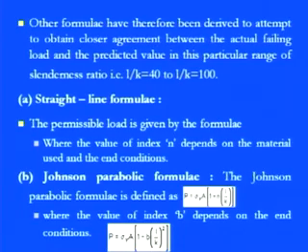But again, with all the nonlinearity and the realistic nature, we need to incorporate nonlinearity in calculating the crippling load in the Euler theory, or we can say we need to incorporate the eccentricity. Then we can figure out, if the eccentricity is in microns or even millimeters, how it will introduce the moment and add up in the final crippling load, so as to calculate the buckling in a realistic way.